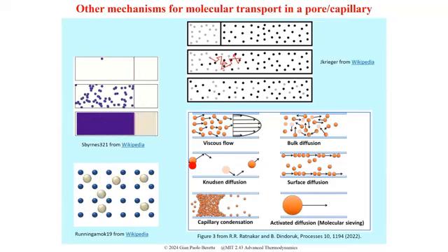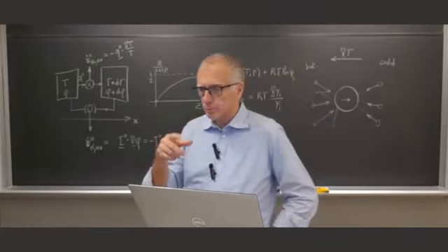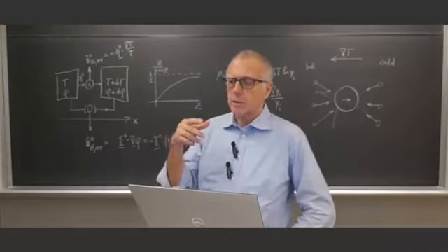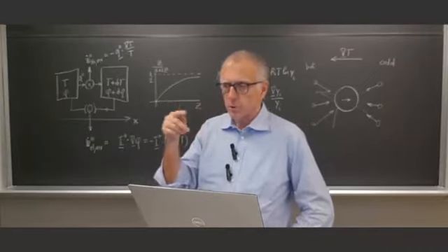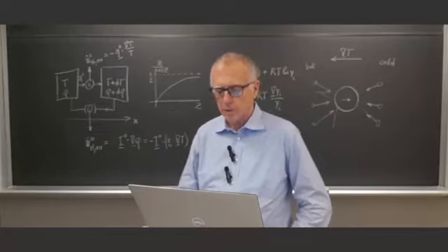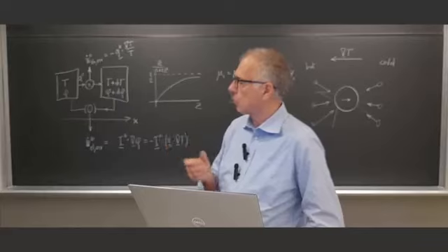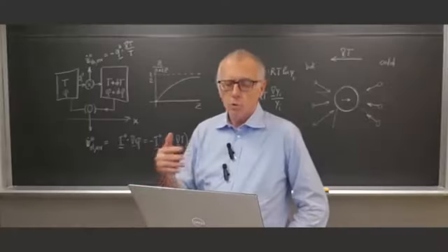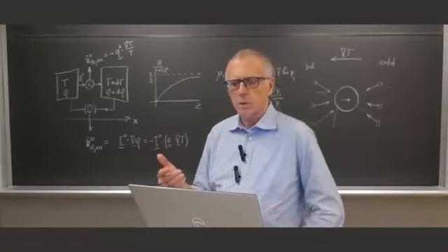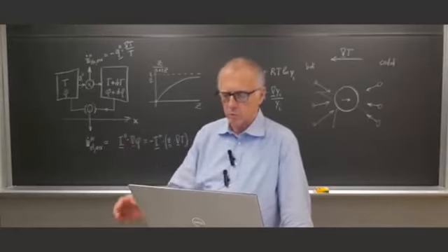So if the Knudsen number is very small, then your particles, let's say, make at least 100 collisions before traveling a distance of the order of magnitude of your device, which could be the diameter of your pipe, then we are safe, and you can make the continuum assumption that we have made in what we've done.